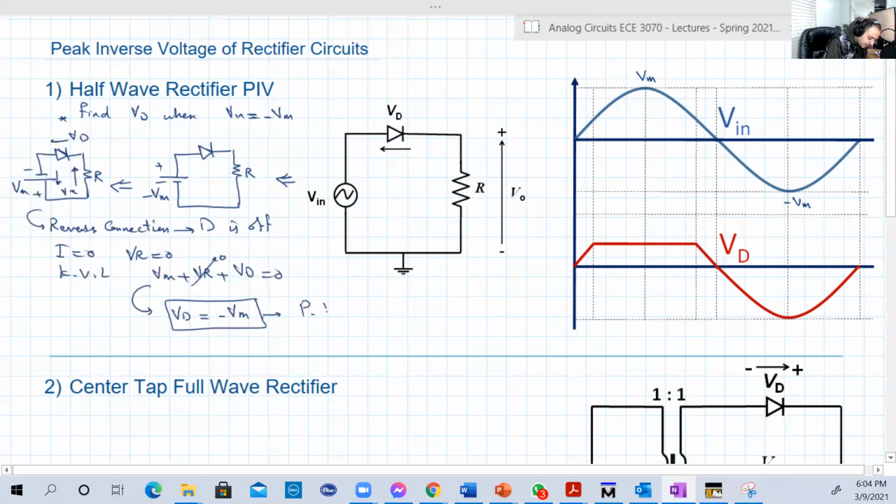So this is basically the peak inverse voltage. So the maximum, as a magnitude, the maximum voltage the diode can see in reverse, or the peak inverse voltage, is Vmax. Okay, so if Vmax is 100, we must buy a diode that has a breakdown voltage as a magnitude greater than 100. Any value greater than 100. Okay. And let's highlight this, because we're gonna use it at the end to compare between all of them.